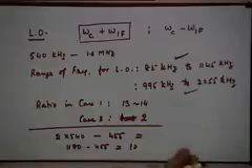Whatever, it's quite large. Whereas the IF filter, which is centered at 455 kilohertz, where the desired signal lies, has a bandwidth of 20 kilohertz or so, right? So it's not an issue. Think about it. If you still have a question, we'll take it up. But we should keep in mind that omega IF should be a lower value than the minimum of that. If you have a peculiar situation, then certainly you should guard against such a situation, but it's not going to arise in this application, right?